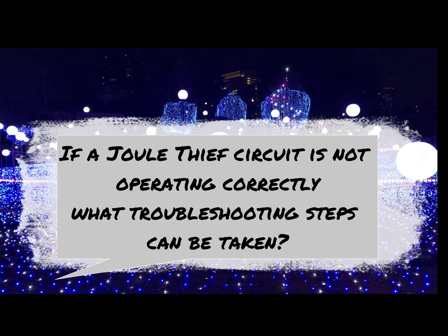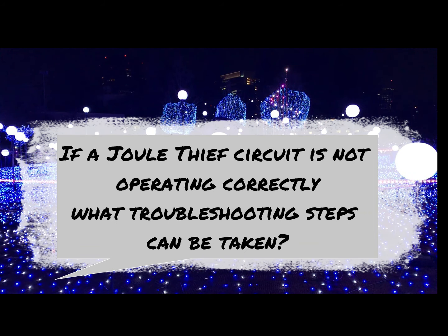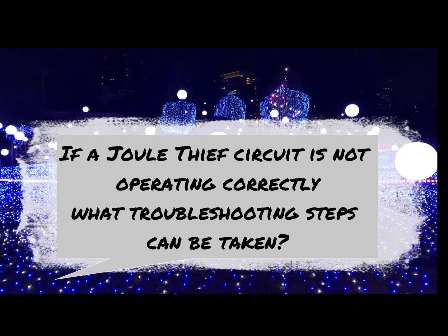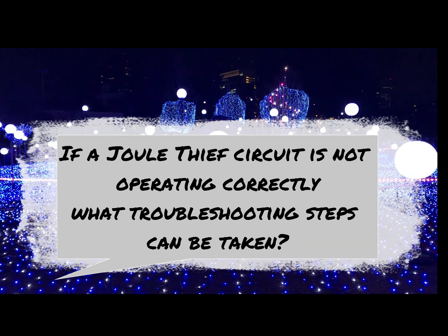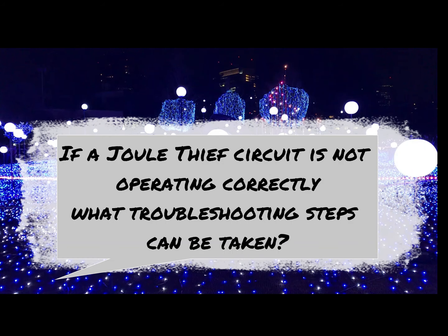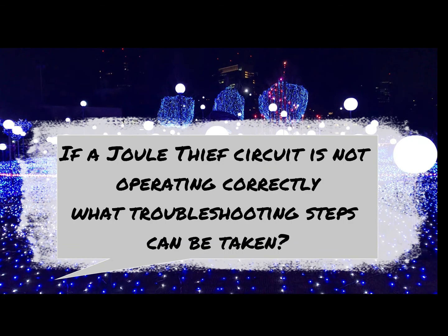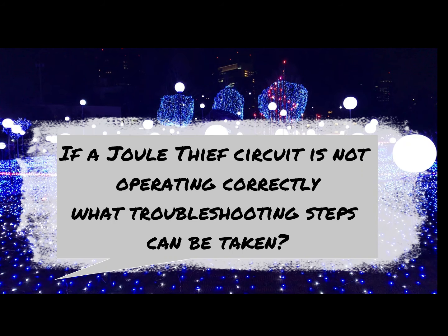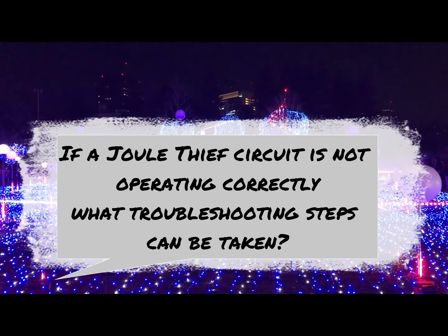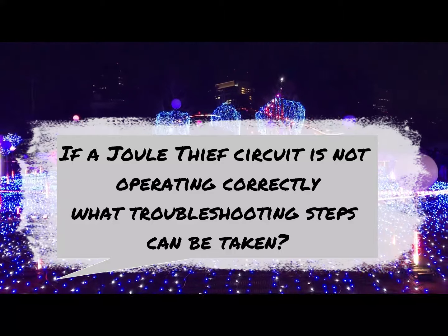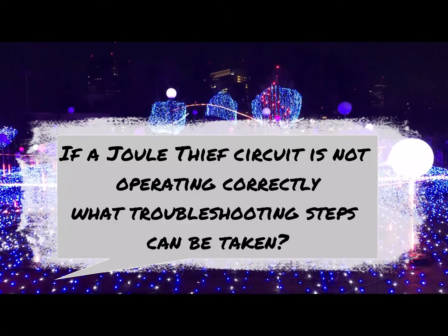Check the resistor. Make sure the resistor is the correct value and is not damaged. Check the coil. Make sure the coil is wound correctly and is the correct size and type for the circuit. Check the frequency. Use a frequency meter to measure the frequency of the circuit, and make sure it is within the expected range. Check the voltage.